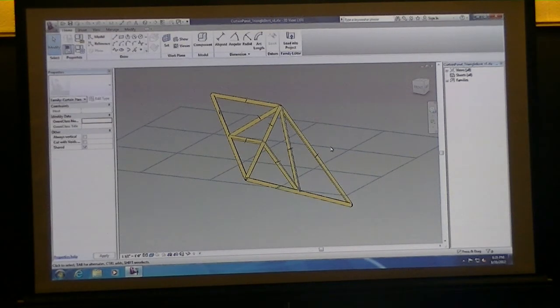So really the strategy is understanding how to work with the curtain panel, which is this pattern-based grid system, and working within that can then allow you to divide up your surface and then apply it to just anything, whether it's a complex form or a flat surface or even some sort of volumetric form. As long as you can divide it up into a grid structure, you can apply this pattern as long as the grids match up. And so today we're going to go through a couple different exercises, not necessarily this one in particular,